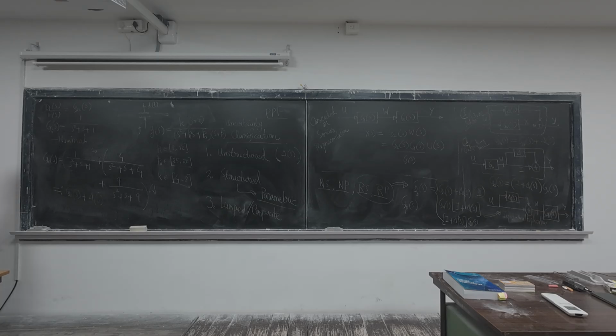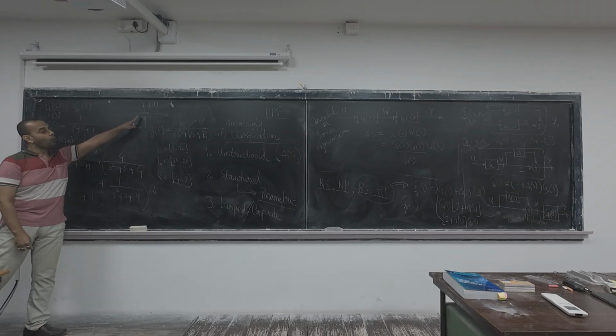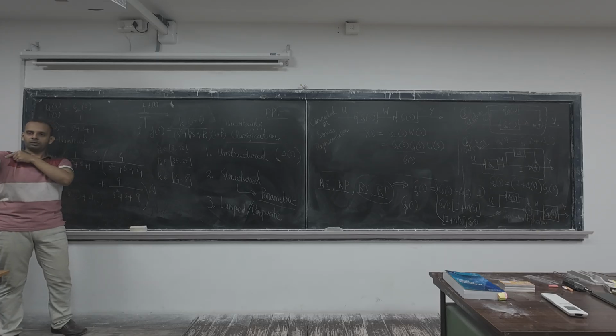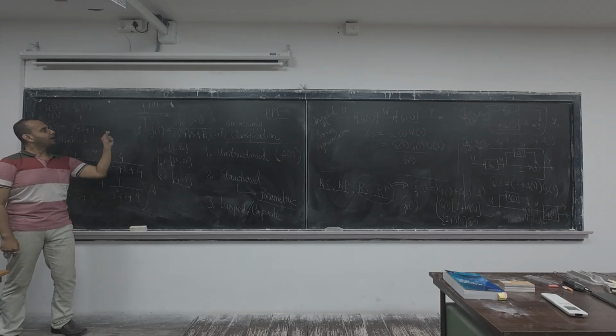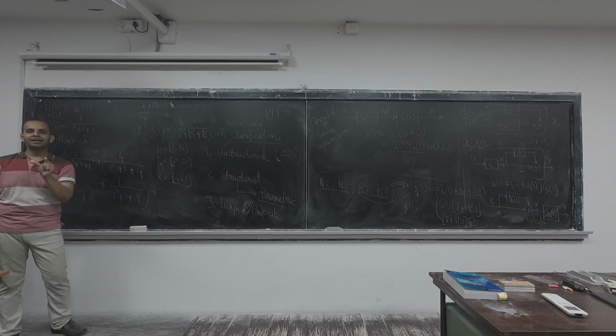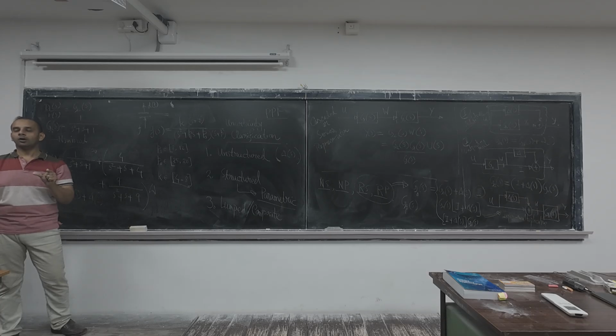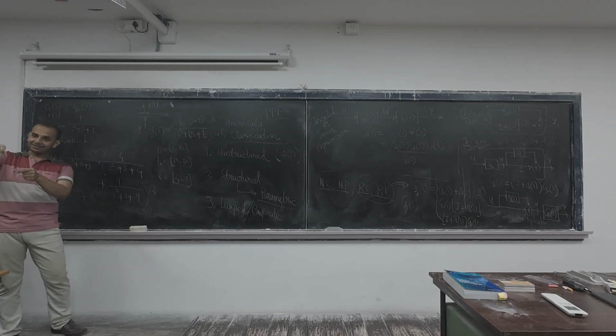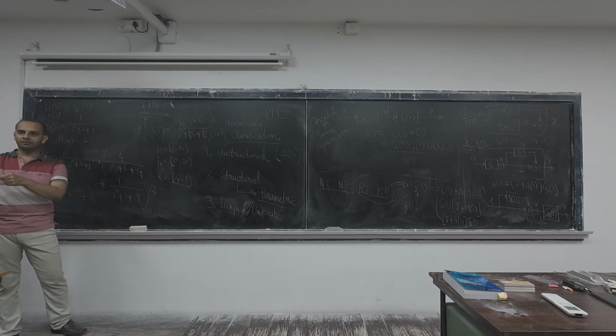Now you have understood. It depends upon how many modes you are identifying from the experiment. That too depends upon where you are placing the sensors. Suppose it is a very long cantilever beam, and then sensors and actuators, you might have heard about the PZT or MFC, piezoelectric transducer sensor, or the microfiber composite MFC. Those kinds of sensors and actuators we apply, and from one side you will be applying force, and on the other side you will measure the vibration amplitude.